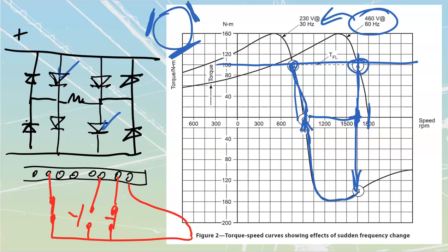When these motors run off the VFDs, we can plug them to a stop. We can control the amount of plugging, the amount of current that we let through, with the SCRs. We can basically decelerate them down and then accelerate them back up in the opposite direction.